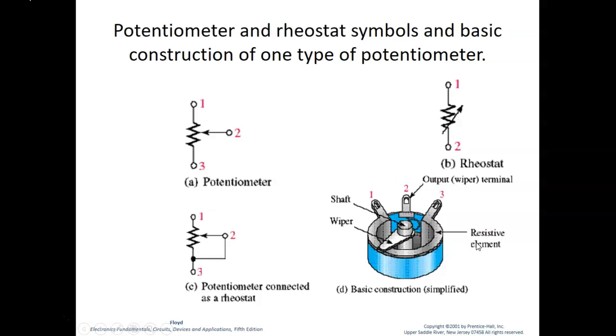Okay, so the way these work, I'm going to go ahead and tell you how a potentiometer works. You get a signal, the full resistance runs between the 2 outermost legs of a potentiometer. That is the full range of resistance. So if I have a 1 kilo ohm potentiometer, I'm going to read full resistance between legs 1 and 3. If I want to vary the resistance and get a variable reading on that resistance, I have to look either between 1 and 2 or 2 and 3.